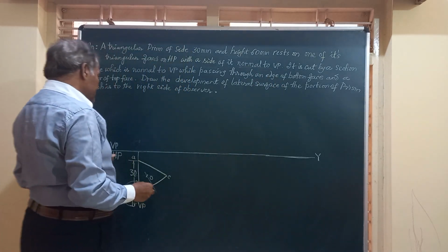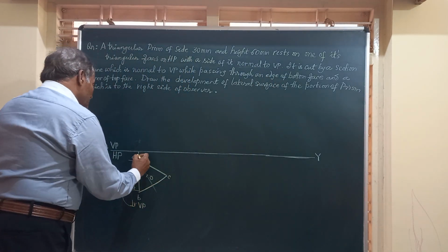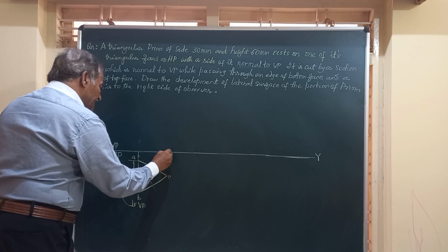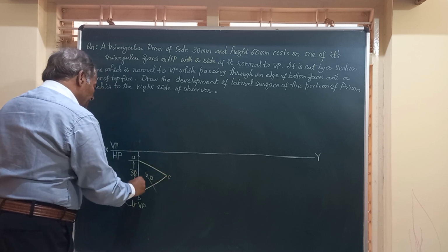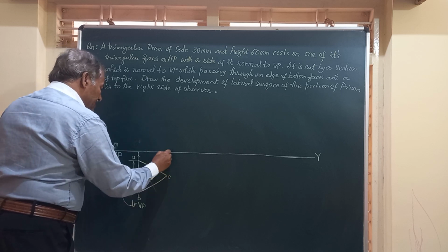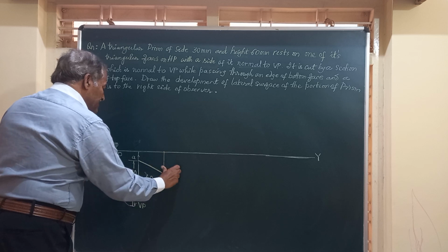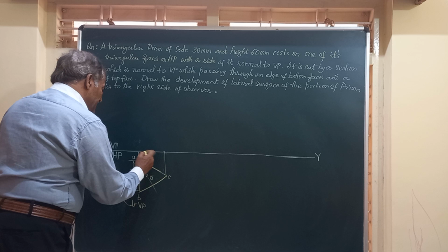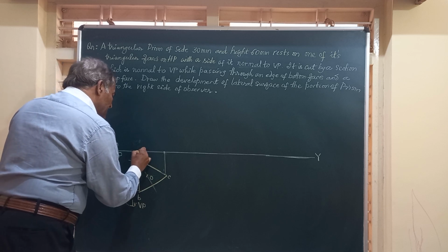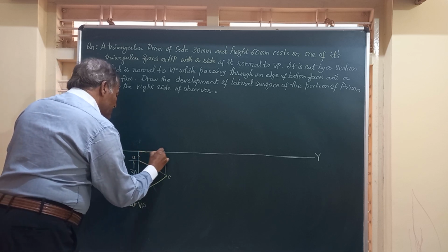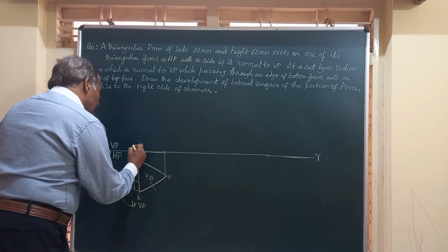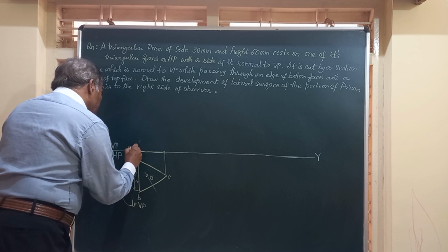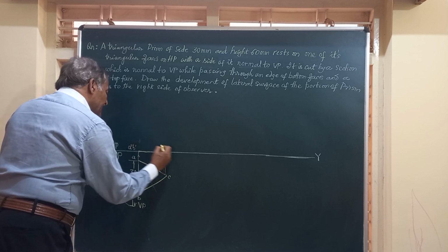And let's see what is the front view for this, friends. So from all this you will write vertical lines. Vertical line from A, vertical line from B, vertical line from C. Friends, we are going to get the top or the bottom face of the solid here. We will show it as A dash, B dash, and this is C dash.